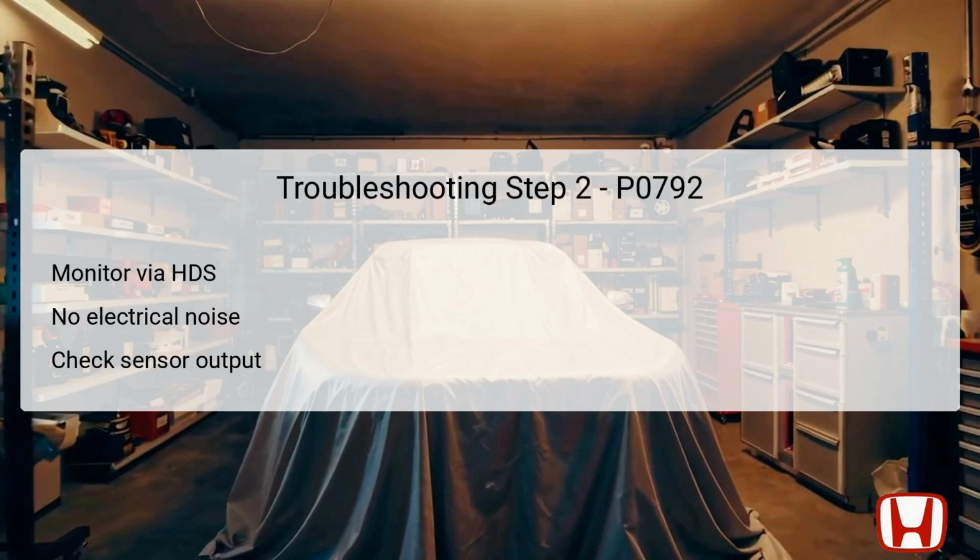It provides insights into its operational status and any discrepancies that may exist. If the signals received by the TCM are erratic or outside normal ranges, the technician can narrow down potential problems, such as wiring issues, sensor failures, or even TCM circuit anomalies. This step is integral for confirming the original diagnosis and guiding further repairs, ensuring effective resolution of the DTC.